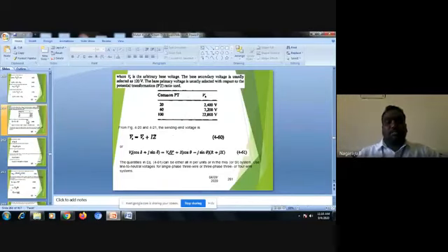When the potential transformer ratio is 20, the turns ratio, I have a base voltage of 2400. When the ratio is 60, that is 60 to 1, I have 7200 volts. When the ratio is 100, you have 12,000 volts. So 20 to 1, 60 to 1 like that. If I have 120 volts, then 120 into 20 gives 2400; 120 into 60 and so on. I am taking the whole primary feeder.